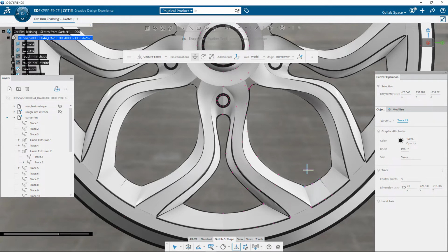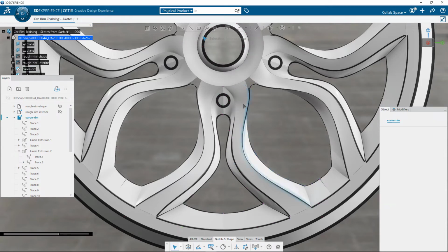When it's done, I will remove the object filter on curves and start to refine the subdivision surfaces with the Mesh Edition command. Once I use topological edition, the link between curves and surfaces is broken, so make sure to do it only at the end of the process.